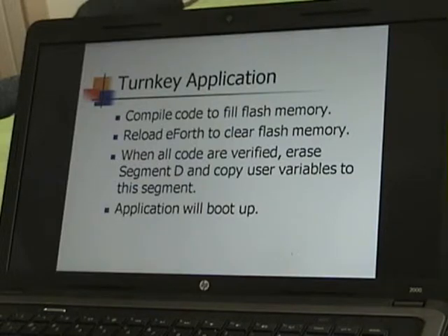And it is very difficult to code Forth words in 512 byte pages. So what I would suggest people do is that you would just add more new code to the flash memory, and if you want to change it, just redefine them until you are happy with the application.